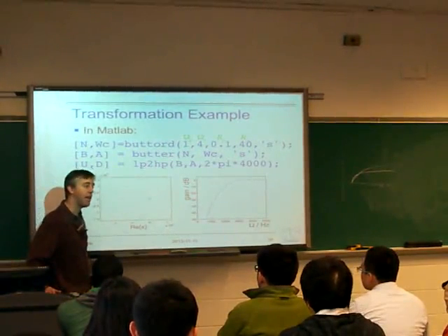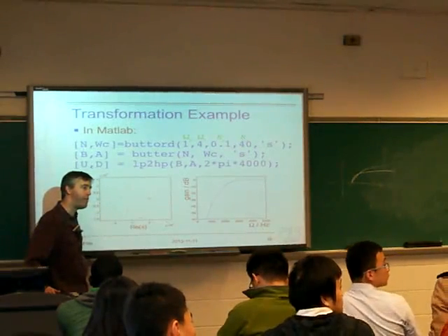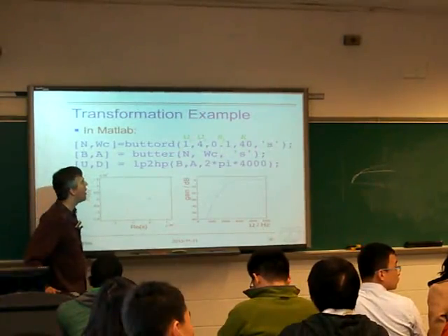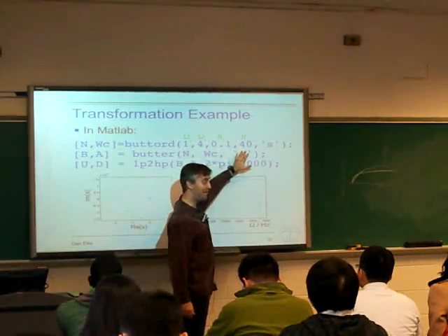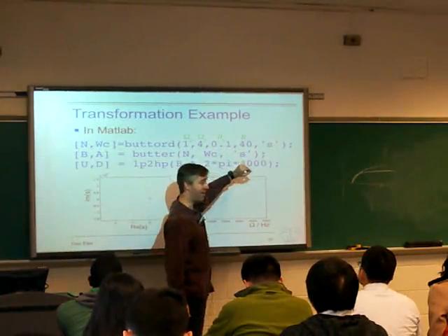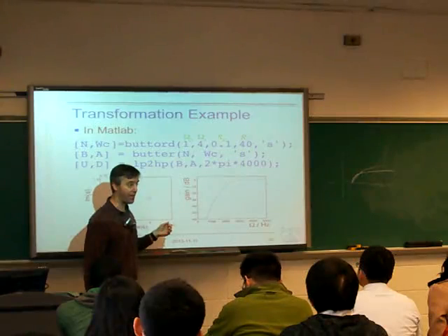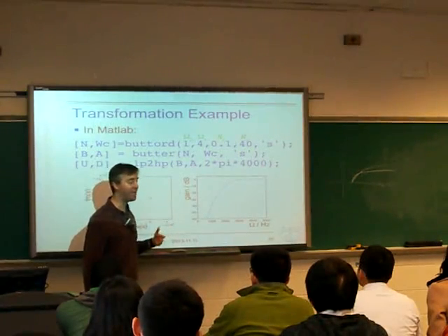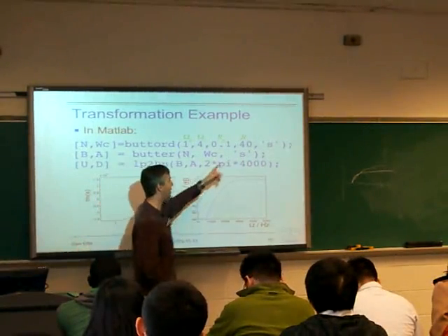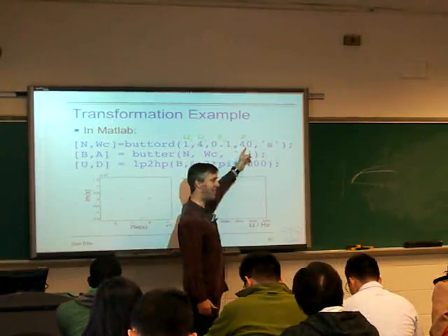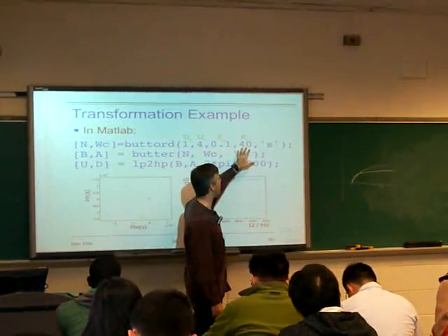Any questions about this stuff? Yeah? We always use the dB value for Rp and Rs. Right. So here, as you've correctly observed, they're specified in dB rather than, say, gain. That is the convention that MATLAB has adopted. And mostly, dB is a much more convenient way of thinking about these things rather than thinking, oh, that's 0.01 in amplitude; you end up with a lot of numbers with many decimal points.